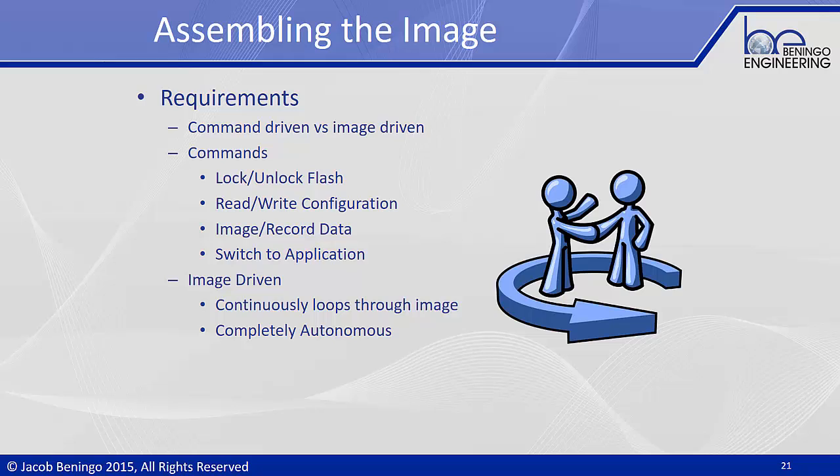Whereas command-driven bootloaders are for microcontrollers that can't store multiple versions of software within their memory space at a given time. So we have to pass it down piece by piece, and to make sure that it all gets there properly, it requires a lot of extra effort. It also makes it more complicated and a little bit more interesting from a software developer standpoint.